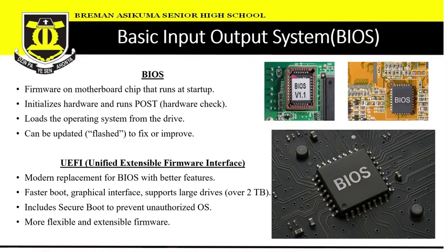So when you turn on the computer, this BIOS that we are seeing here will perform what we call a power-on self-test. It will check if the CPU is working, if the VGA is working, if the RAMs are connected, everything. If any of these are missing, the BIOS can report that this is missing. In the case where there is no RAM, the BIOS cannot POST. Even if there is no RAM, the BIOS can sound an alarm through the buzzer, so that you know there is a problem on the motherboard or with the system.